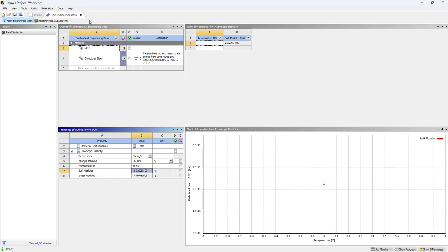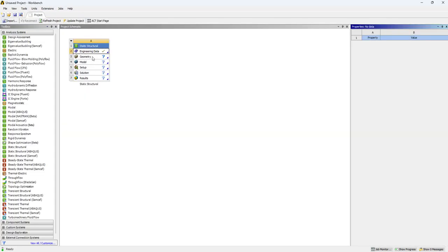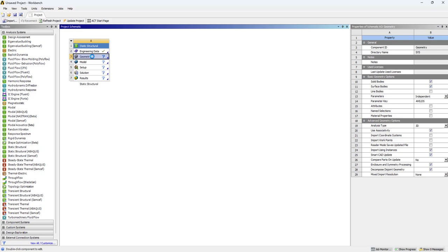After adding the material properties, let's move on to the next step, which is modeling the geometry. For line elements, the analysis type needs to be set to 3D. So you see that ANSYS only has two different analysis types, 3D and 2D. Although in a line element we only model the length, however that length or particular shape of the line can be oriented in 3D